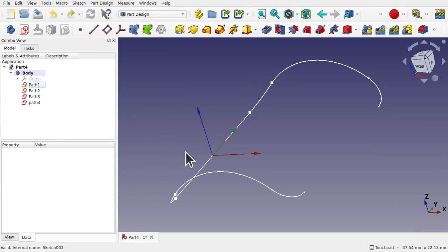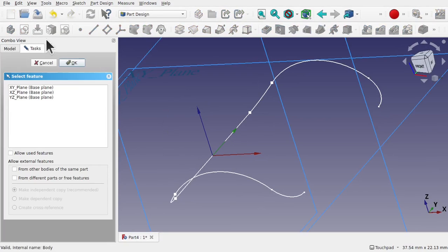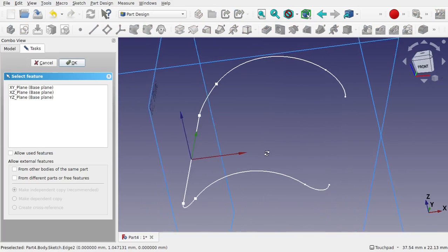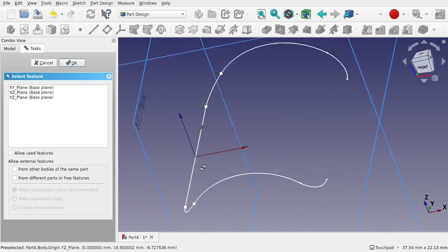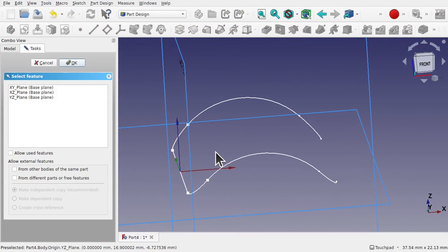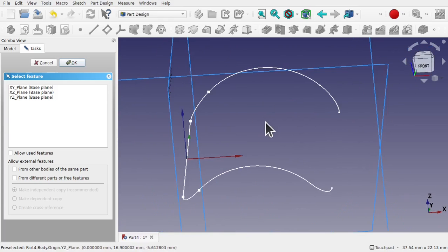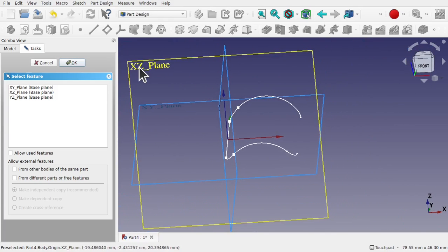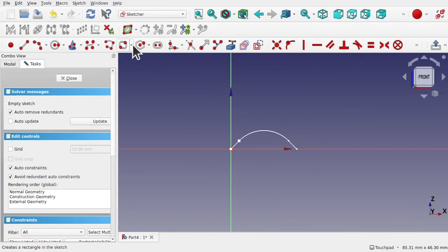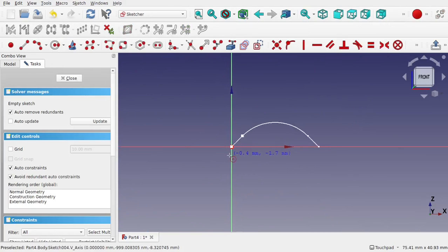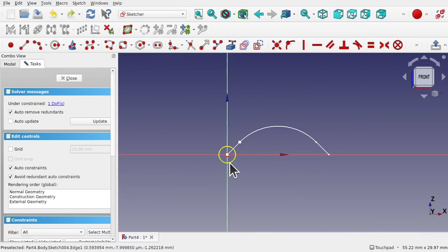Let's create the profile. We're going to do that with a new sketch, and we're going to go along the XZ plane because the profile needs to sit here. So we're going to use a sweep profile. This is the cross section of this piece, which is constant all the way around. XZ plane, and it's basically a circle. So come in, create the circle attached to the center point, and set the diameter of this to 2 millimeters.